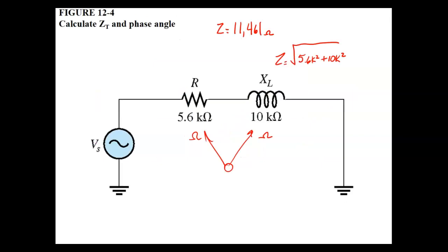So what would the phase angle of the circuit be? That would be 29. It's going to be reactive over resistive. We can use reactive voltage over resistive voltage, or since voltage and opposition in a series circuit are directly proportional, we could use the 10K and use the arc tangent of reactive over resistive. It says R over S? Not for the angle.